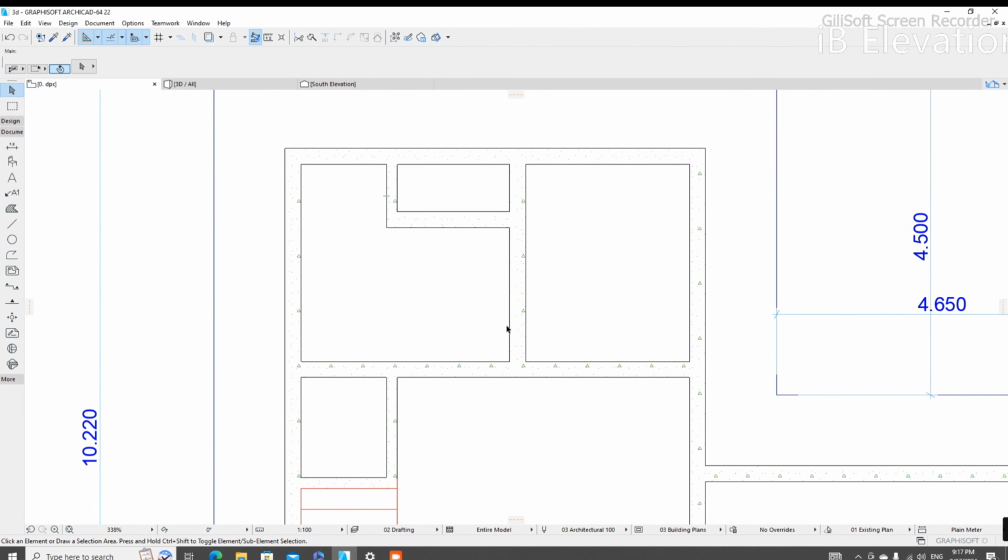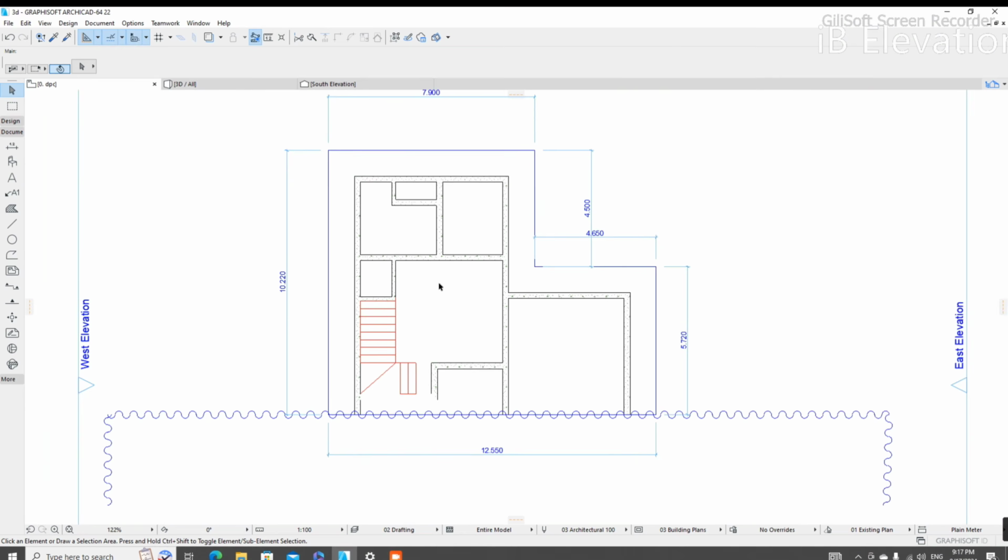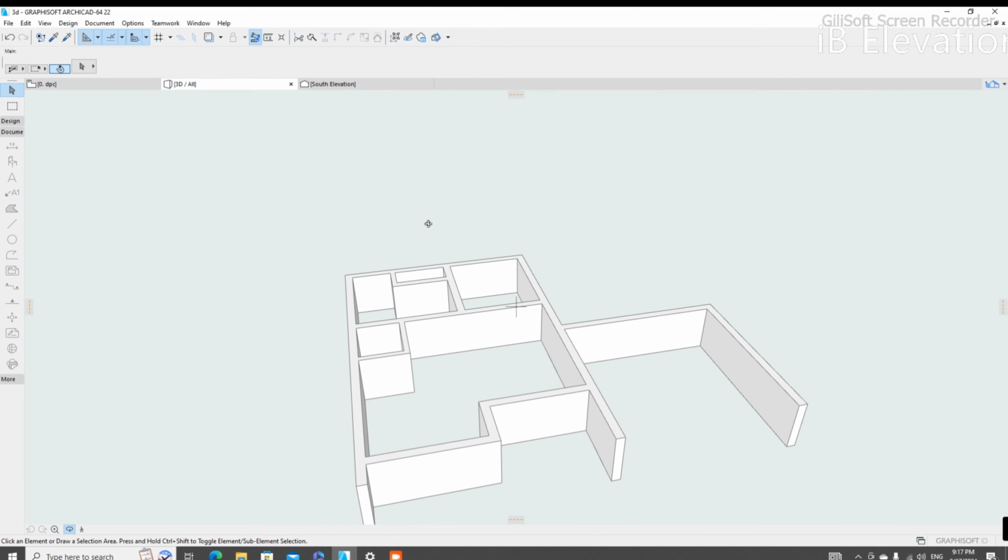So we cannot have this as a balcony, and we cannot have this section be the kitchen completely, because we're going to have a door here to access this kitchen, and another door here to access this. So we are using an L shape for the cabinet. Okay, that's perfect. We're going to do that on the ground floor, because this is still the DPC level.